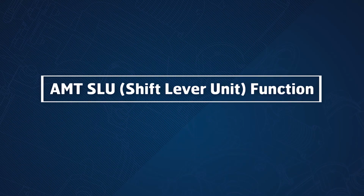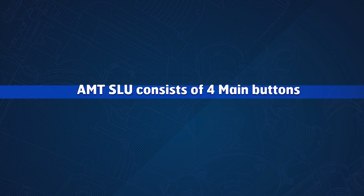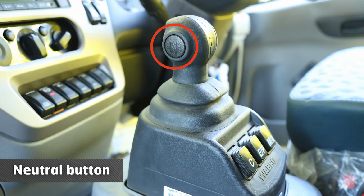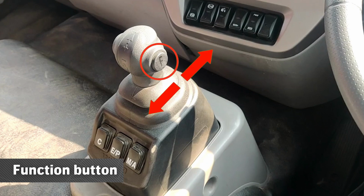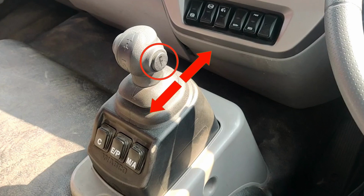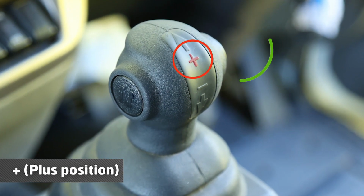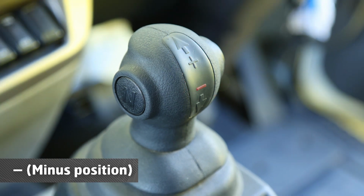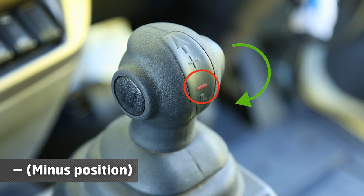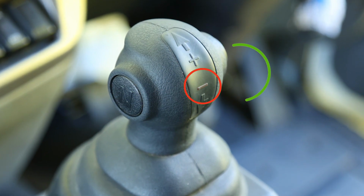AMT SLU, shift lever unit, function. The AMT SLU consists of 4 main buttons. Neutral button, brings the vehicle to neutral. Function button, for launching the vehicle the first time in forward and reverse direction. Plus position, the lever can be tapped in the forward direction to select forward gears. Minus position, the lever can be tapped in the backward direction to select reverse gear or lower gears than the current gear.